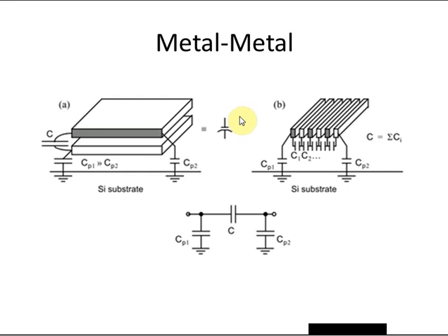Another thing I want to point out as well, final thing, is that as with resistors, depending on the particular manufacturing process, some will have special layers available that are there for no other reason other than to implement high density capacitors. For example, what used to be popular was having a second polysilicon layer just above the main gate polysilicon layer, again separated by relatively thin dielectric. Now, polysilicon is not used as often as some other layers that are higher up in the metal stack, providing lower parasitics. So when available, those obviously provide a very good alternative, but of course come with some extra cost.